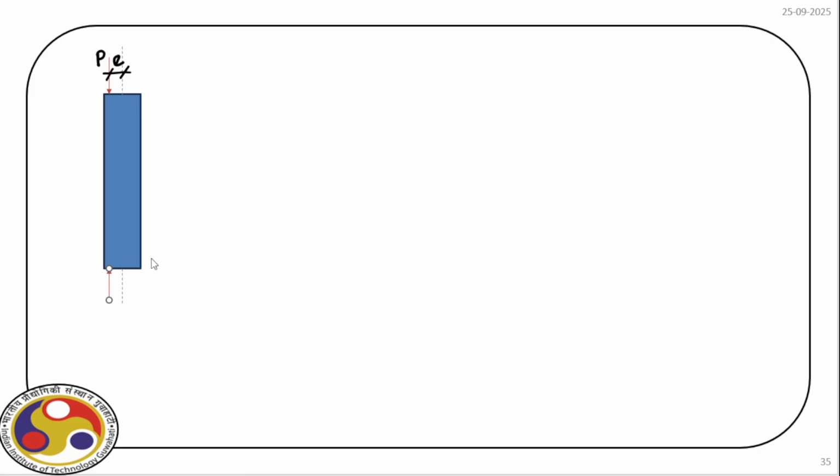So we have a hinge here, and we also have a hinge there. We can change the boundary condition, so that's not an issue. Let us consider hinge at the ends. Now, our first task is to derive the governing equation along with its constants, which we know from our previous lecture. So let us try that, and for that let us first redraw the column as a line element.